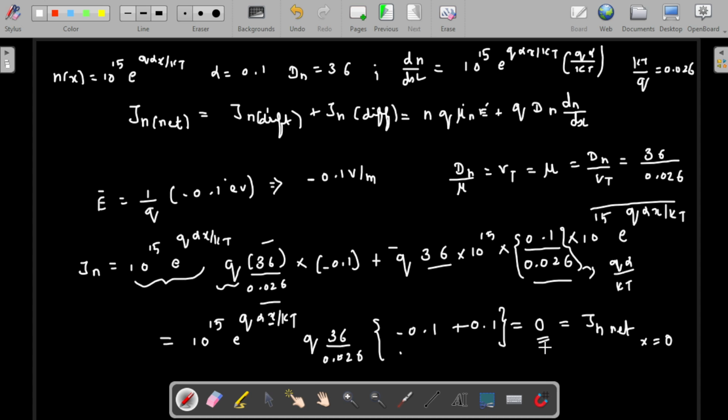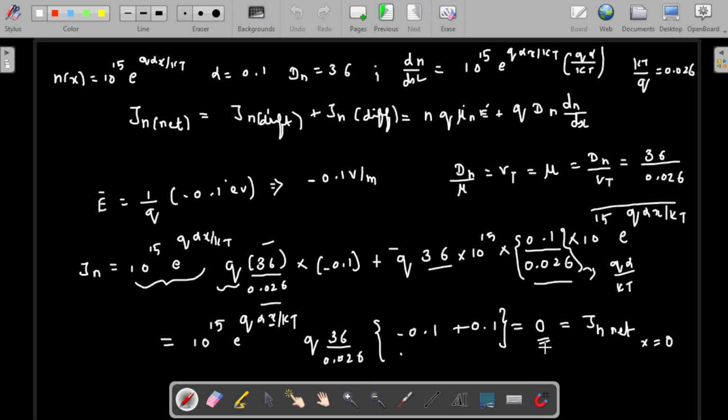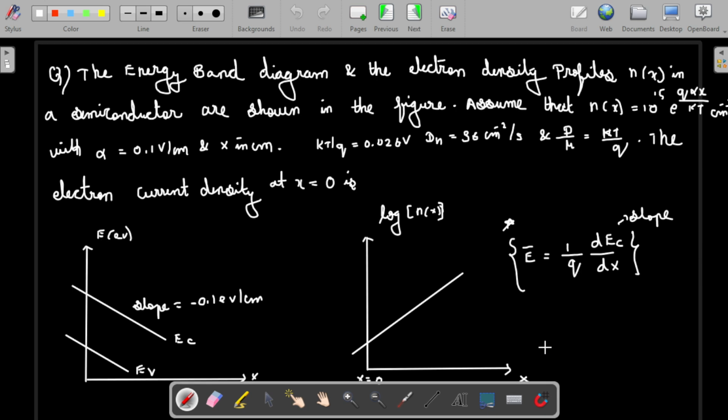This is not only for N type, similarly for P type. I hope this question gives you some understanding; huge numericals will be there, but that is not the intention I am trying to convey here. Some guys may smartly reason that there is no external supply voltage given, so from the graph I could clearly see there is no variation in the Fermi level of the acceptor atom or donor atom, so the J-net profile will be equal to 0. That way we can also answer, but most of the time it may not result in a good way.